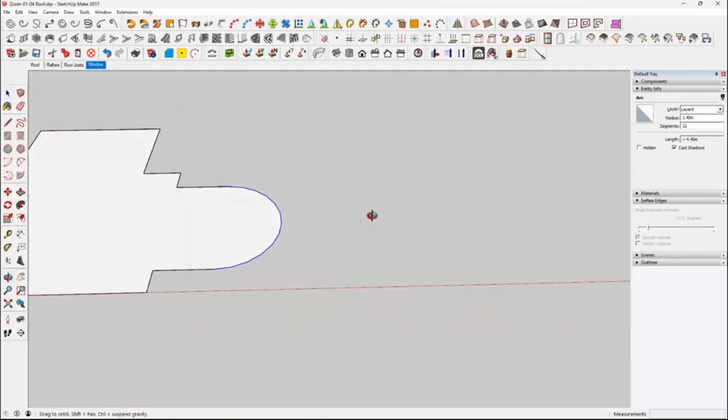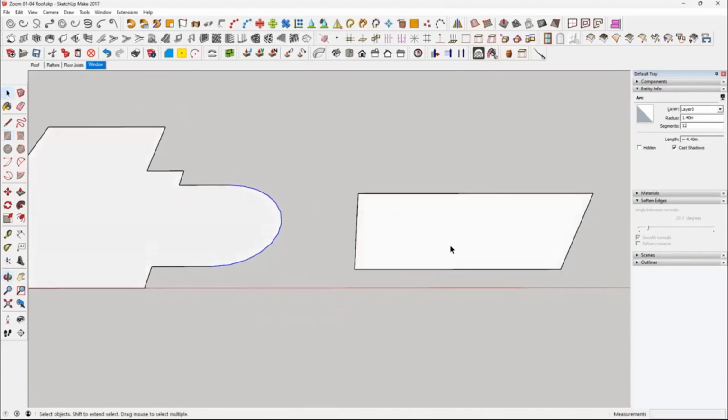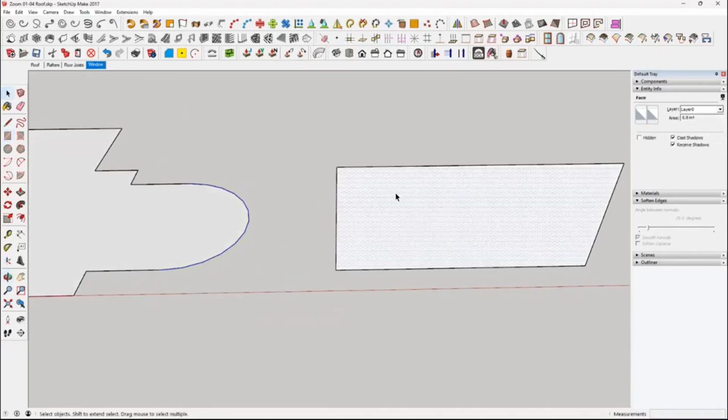So what we need to do is draw a square in front, and not on the blue axis, but we want to stand it up. So we'll tap green and we'll start drawing up, and then we'll put our dimensions in. Bottom right hand corner, so we want 4.4, and we'll do it 2 meters high. So there we go. So in theory, this will wrap around this curve.